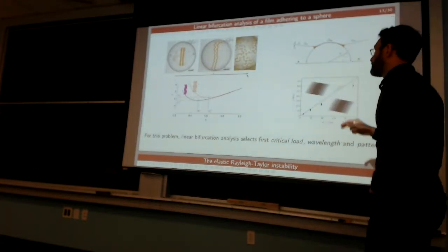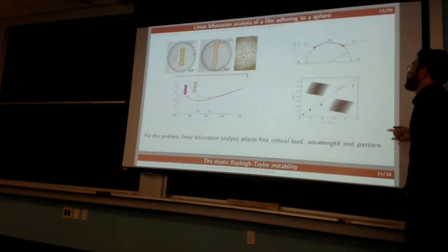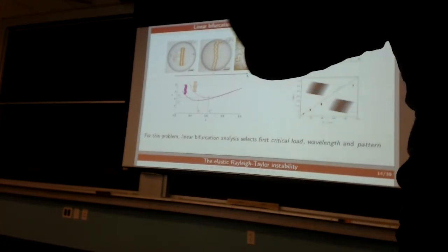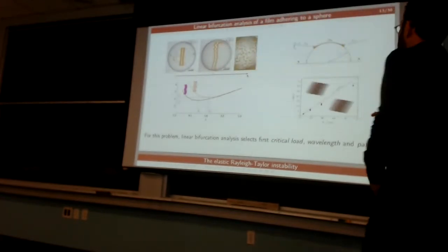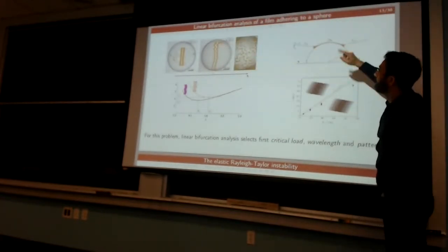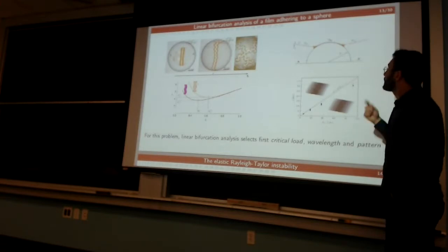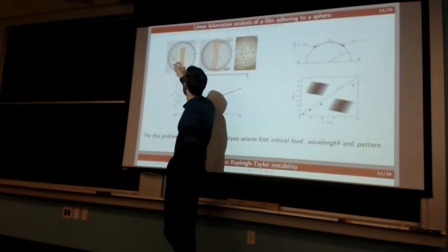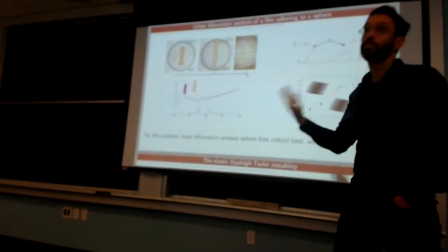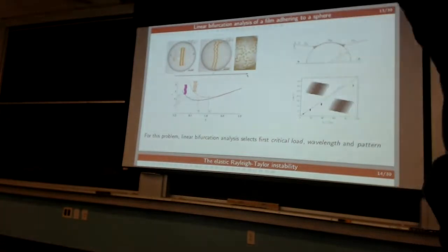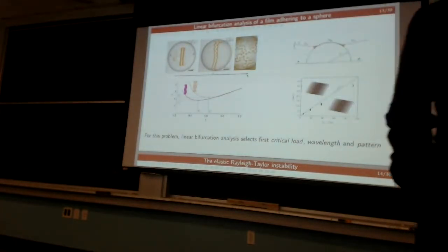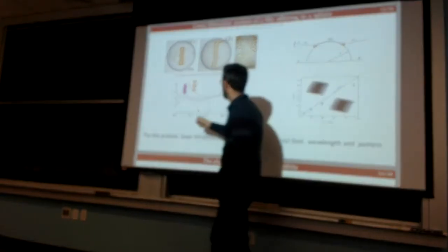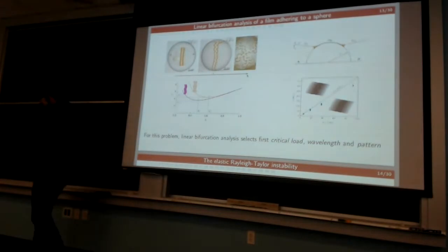So we have to solve these shell's equations in axisymmetric geometry. Of course, it's a lot easier because if it's axisymmetric, it essentially only depends on one variable. Everything is invariant along this theta direction. So that can be done, and then you can analytically calculate these configurations. And then we do the trick of looking at the linear bifurcation criterion, and when we do that, this ends up with something pretty similar to that.